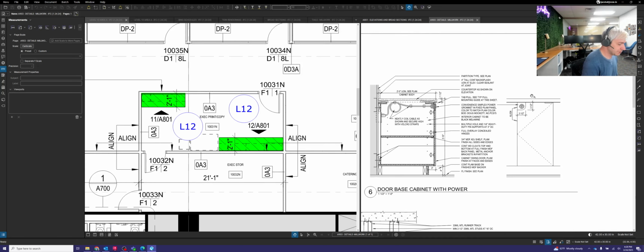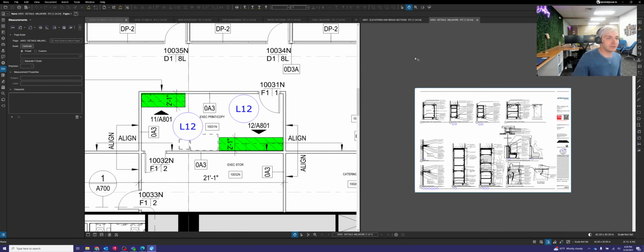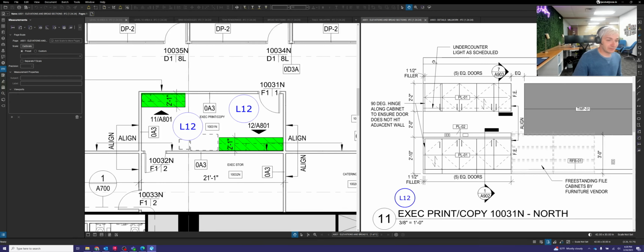We talked about finishes, hardware, equipment, and plumbing. Those are all super important. Usually you can find that information through the use of the equipment schedule in partnership with what you're seeing in your elevation view. So in this particular elevation view, we see EQ7 right here. That stands for equipment number 7.